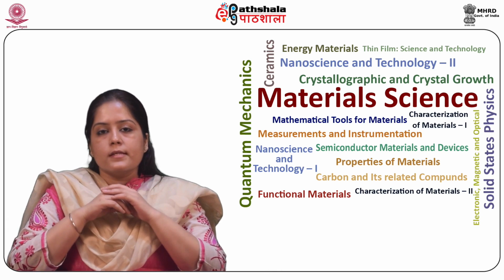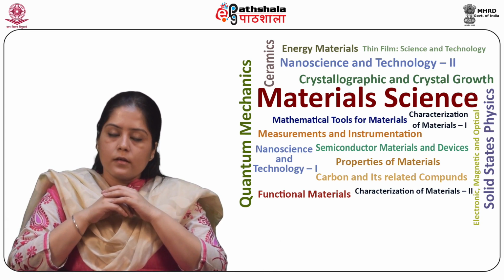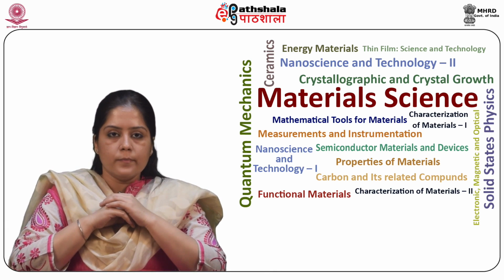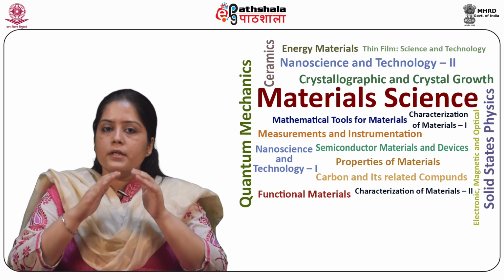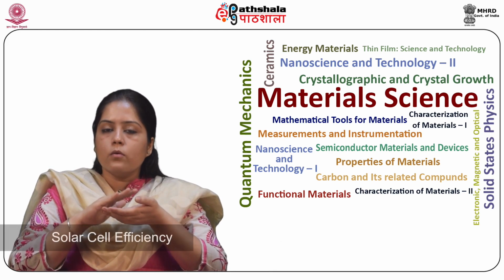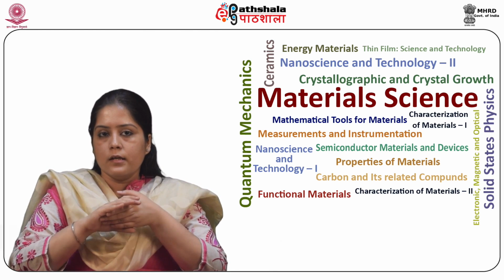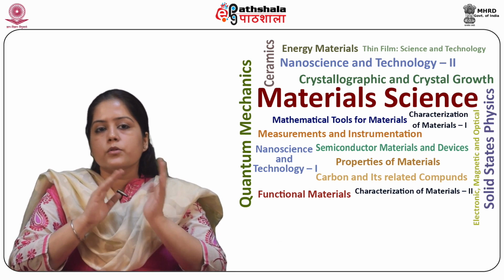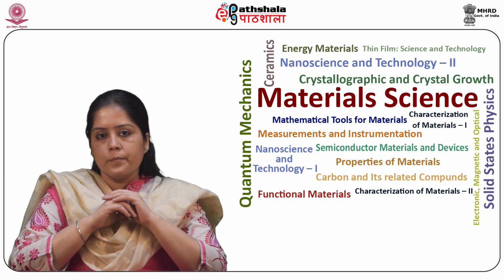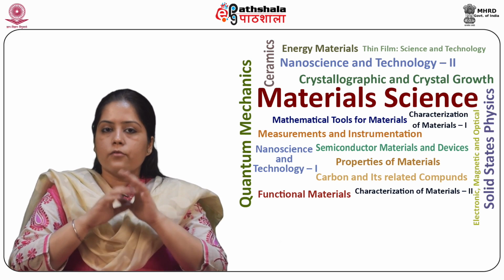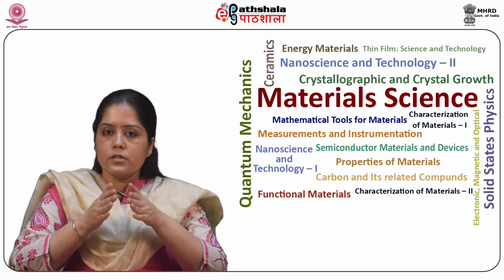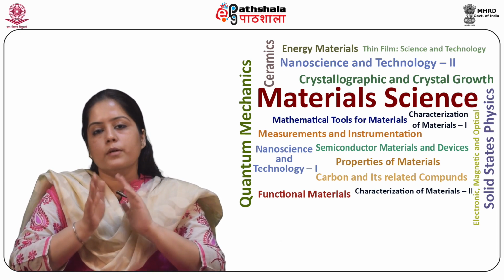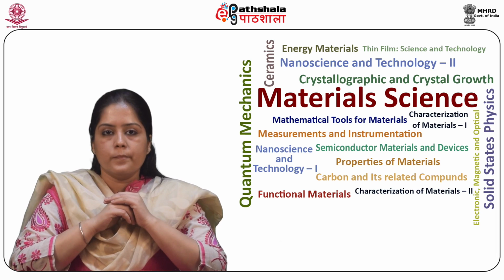So students, let us summarize what we have learned in this module. The upper limit to the solar cell efficiency lies within 26% to 29% and occurs for a band gap in the range of 1.4 electron volt to 1.6 electron volt.